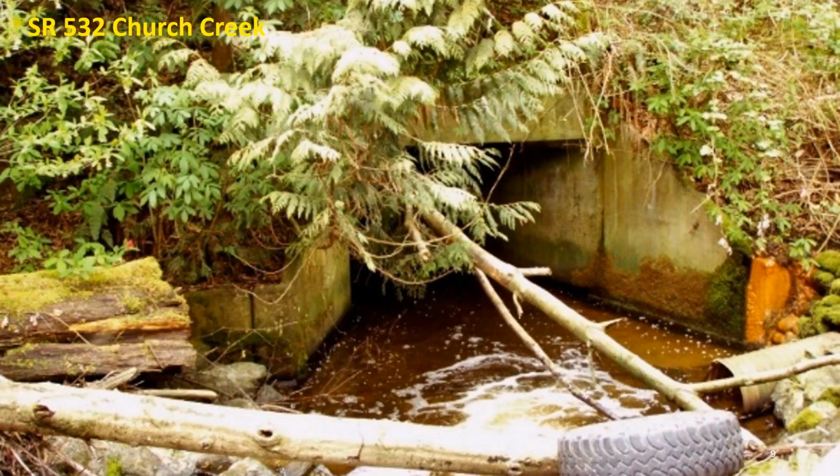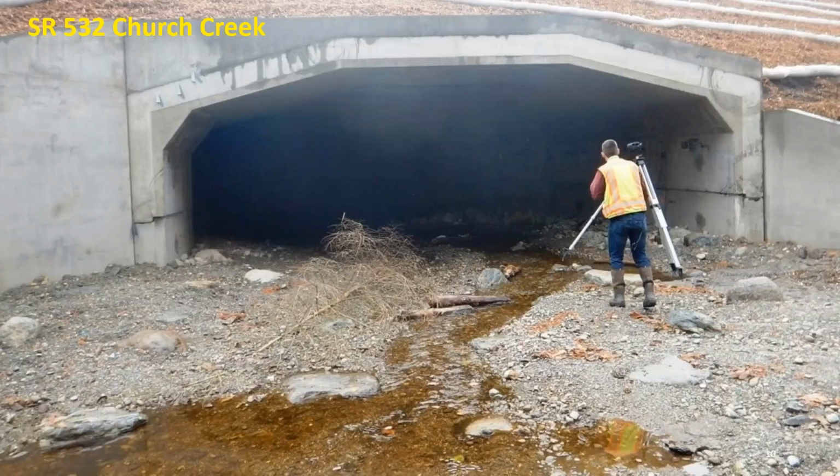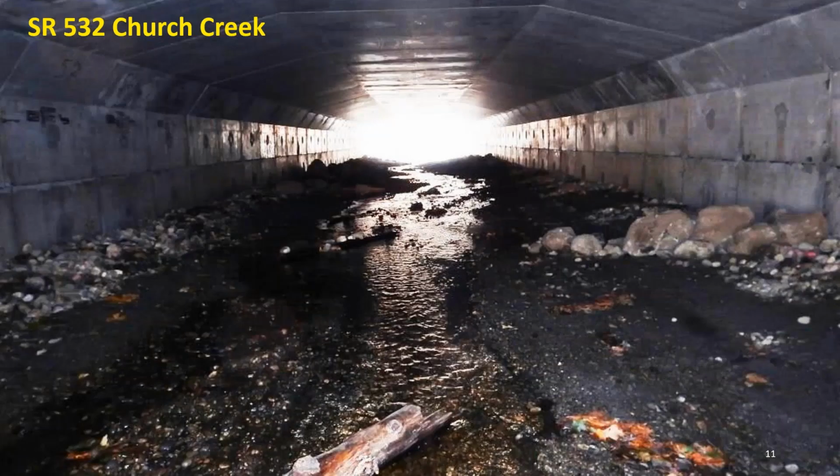Here's another example, SR 532 Church Creek. You can see all the barriers and debris in the way here. There's a lot of woody debris that comes downstream and ends up clogging and choking up this passage. Here's a picture during construction. This is built with a precast three-sided structure to provide a much wider opening to address any sort of debris that comes downstream. And here's the inside of the completed structure. You can see the precast on the outside there. This whole project was built with a 2-week closure, so very rapid construction using ABC.